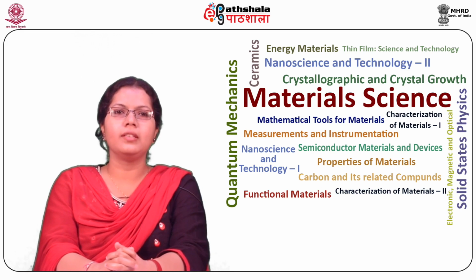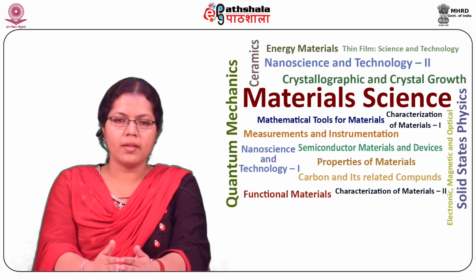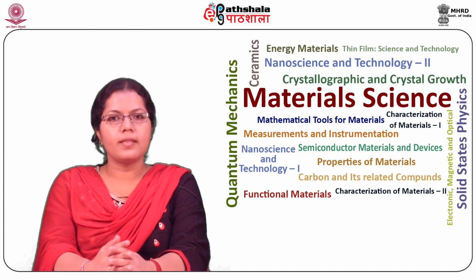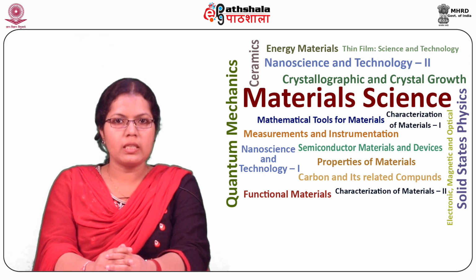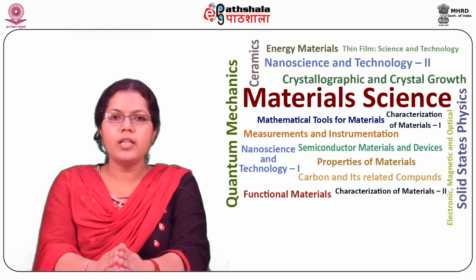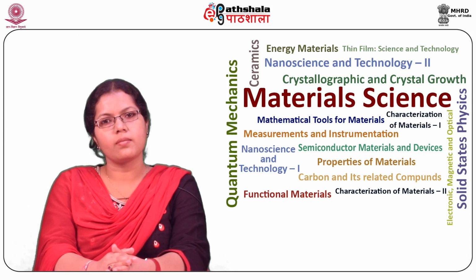Students, now let us start with the inductors. First, the standards of inductance. Both the self and mutual inductances depend upon their physical dimensions together with the number of turns in the coil. For the designing and construction of inductance standards, a few considerations must be taken care of, such as the design and construction should be such that a rigidly standard accurate formula exists relating the value of inductance with the physical dimensions.